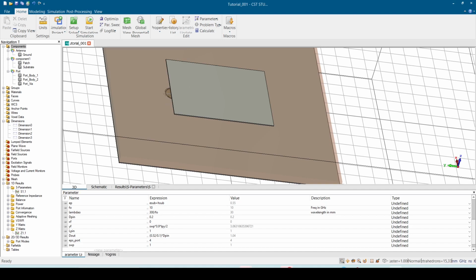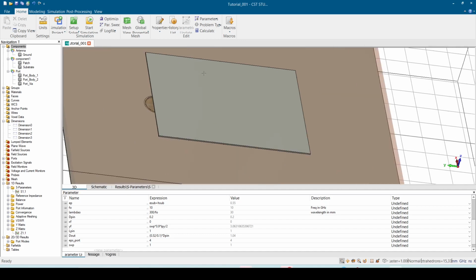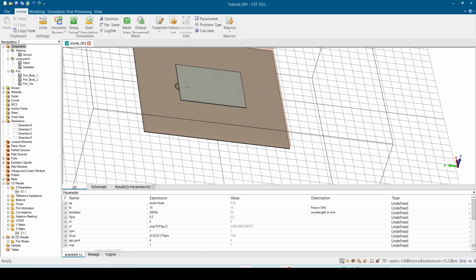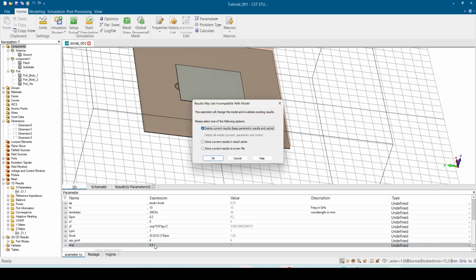So the location gives you, if we fix the patch width, what's the best place to feed. And when we reach this location, we can optimize together with the location of the feeding around in the y-axis, and at the same moment also the width of the antenna, given the other considerations in the design. So for now, I can fix this sweeping at 0.3.